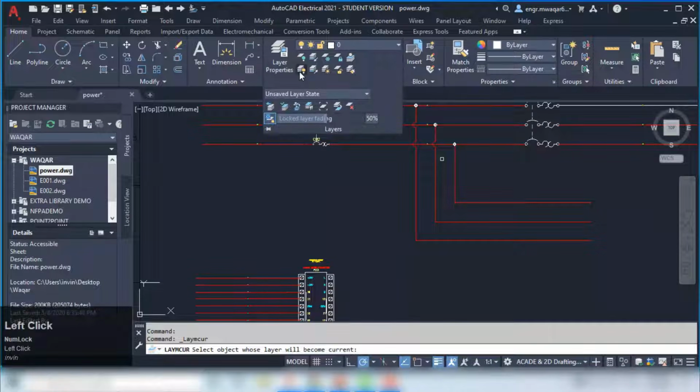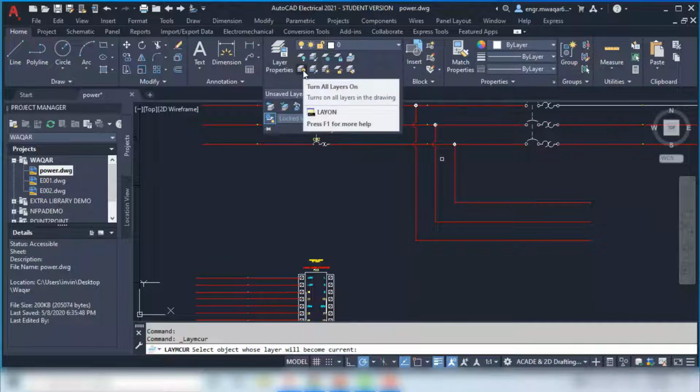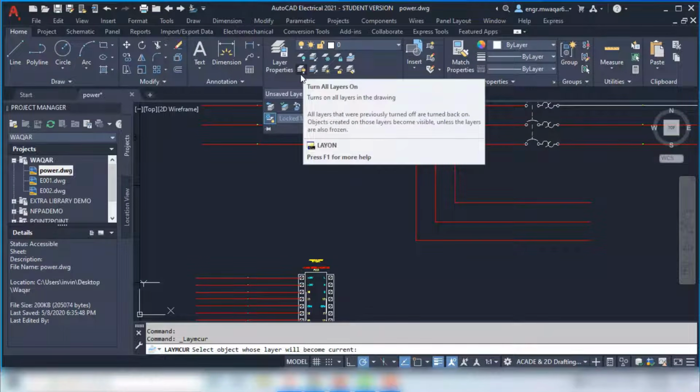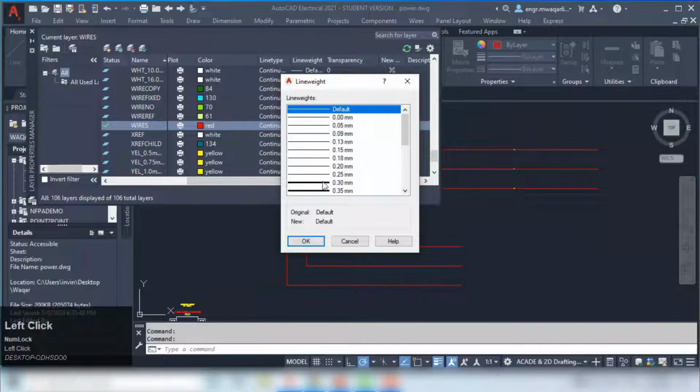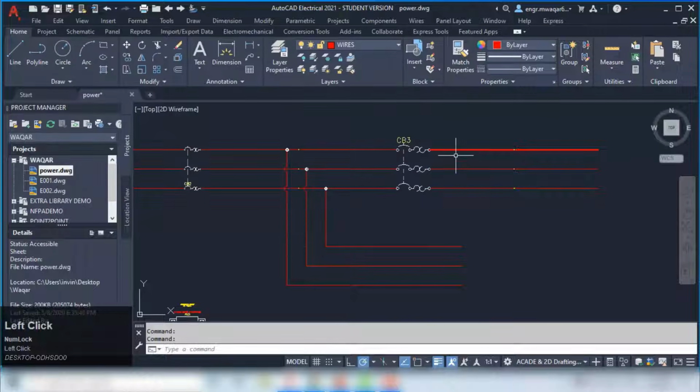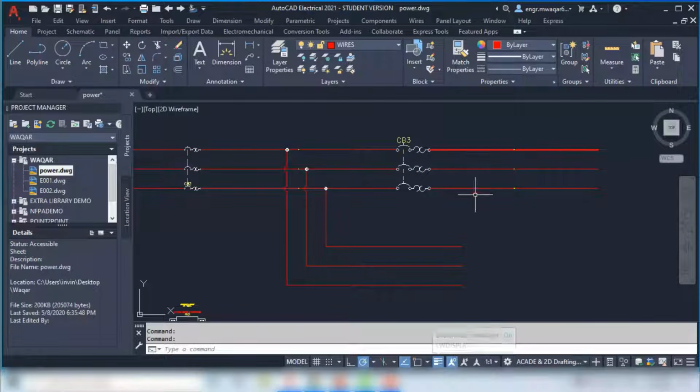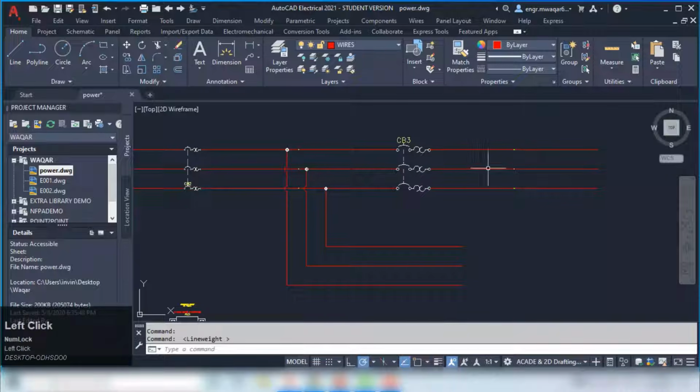It focuses your attention. And speaking of visual detail, let's touch on line weight. That's another common operational trap. Oh, yeah. You can define the line weight in properties. Maybe you set your wires to 0.30 millimeter, but the critical detail is that AutoCAD defaults to hiding the visual representation of that thickness.